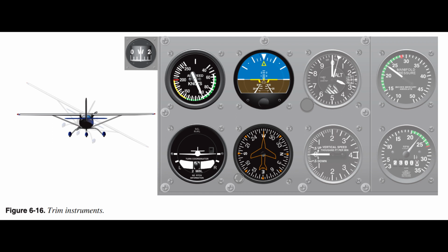Instrument crosscheck. The first fundamental skill is crosschecking, also called scanning or instrument coverage. Crosschecking is the continuous and logical observation of instruments for attitude and performance information. In attitude instrument flying, the pilot maintains an attitude by reference to instruments, producing the desired result in performance. Observing and interpreting two or more instruments to determine attitude and performance of an aircraft is called crosschecking.